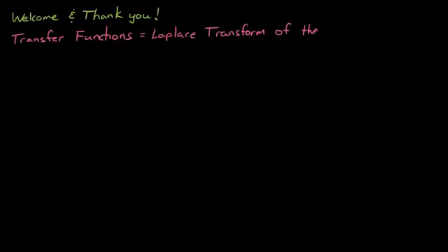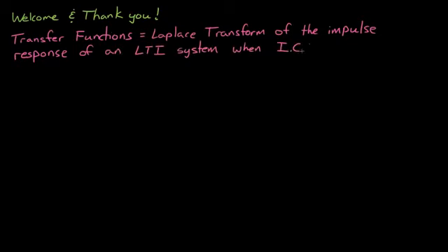In this lecture, I'm going to describe transfer functions and how control engineers use them to model elements like filters and actuators in order to simplify control system design and analysis. In the simplest description I can find, a transfer function is the Laplace transform of the impulse response of a linear and time invariant system when you set the system initial conditions to 0.